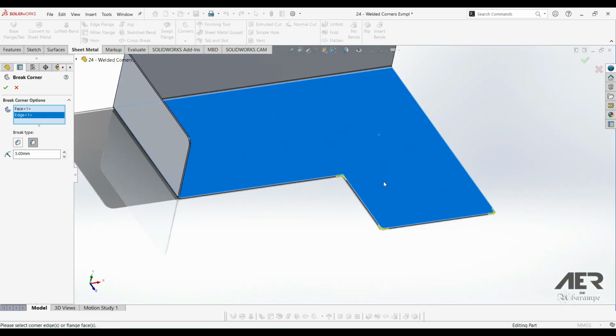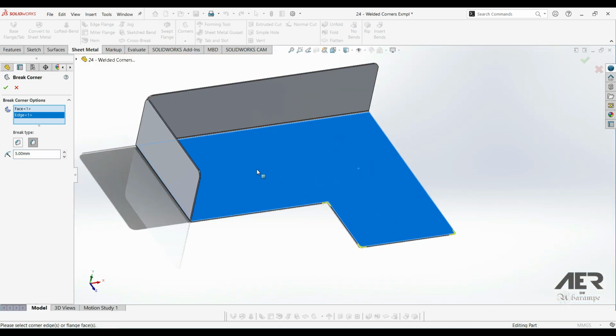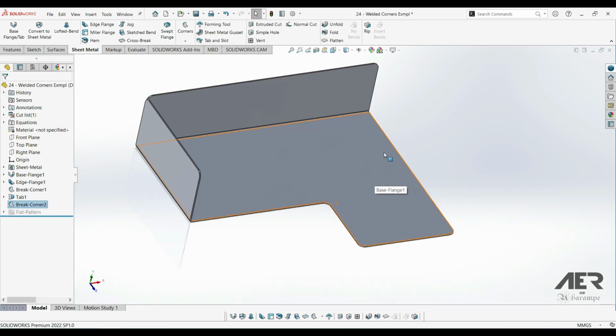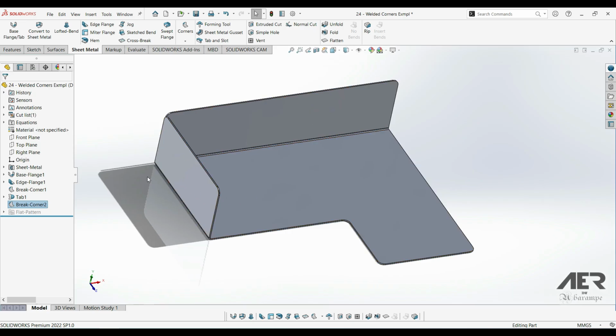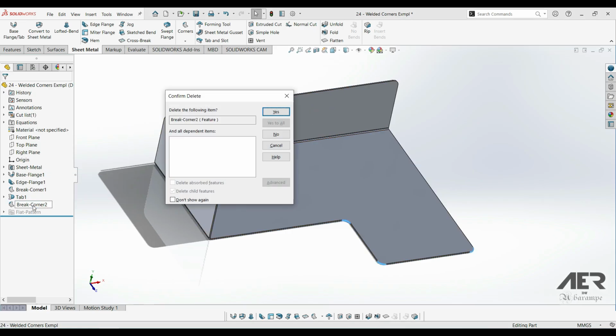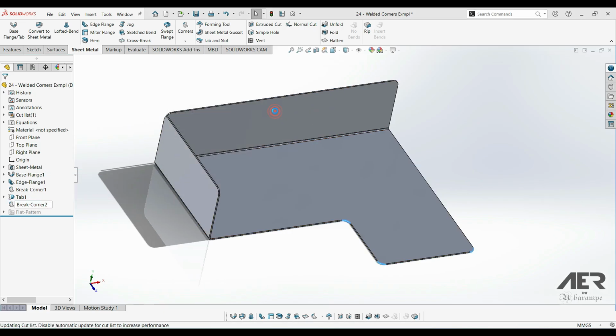We might be wondering a little bit what the point of this is. Isn't it just the same as the fillet or the chamfer tools? And it's a good question really. The main advantage of this is that it's much faster to do it like this. We can just click on the face, and all of the corners on that face will be selected.